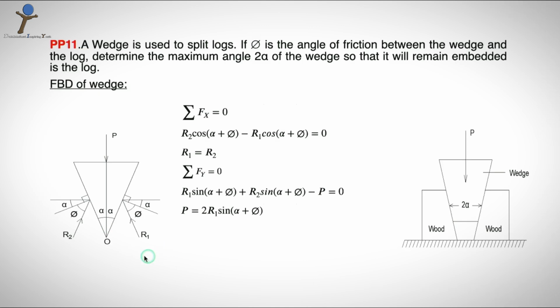That means when the wedge angle is equal to the frictional angle, that's the maximum angle of the wedge, so that it will remain embedded in the log.